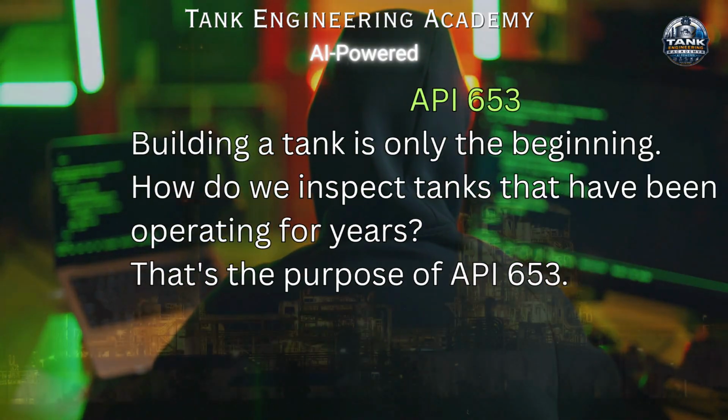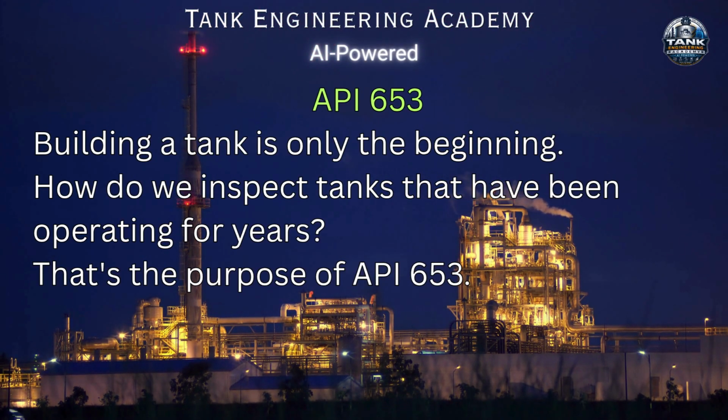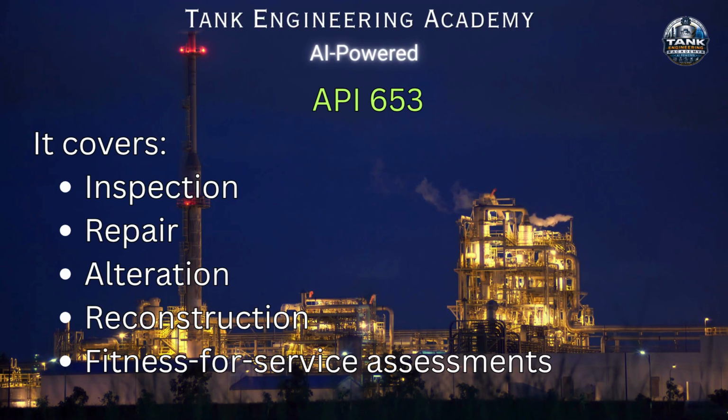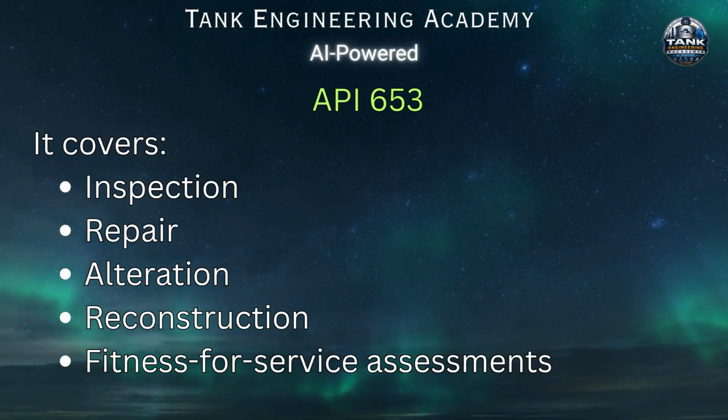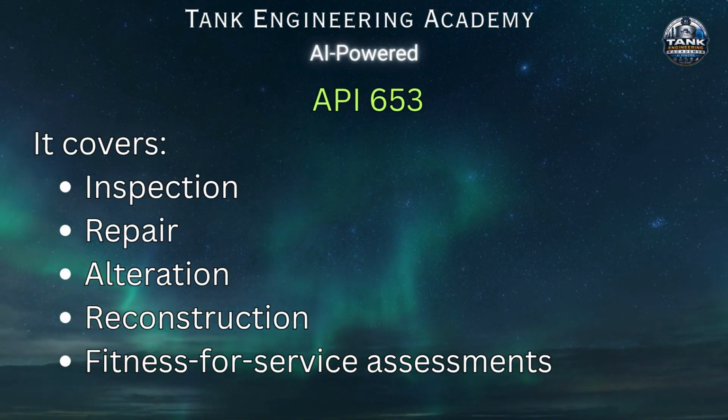API 653. Building a tank is only the beginning. Now, how do we inspect tanks that have been operating for years? That's the purpose of API 653. It covers inspection, repair, alteration, reconstruction, fitness for service assessments. API 653 helps extend the safe operating life of storage tanks.